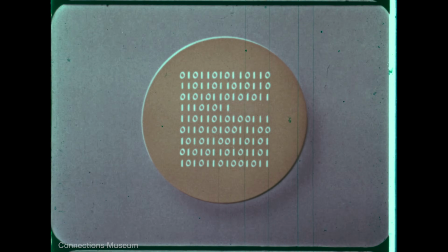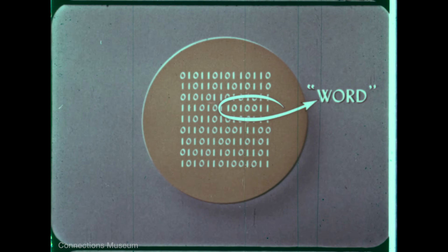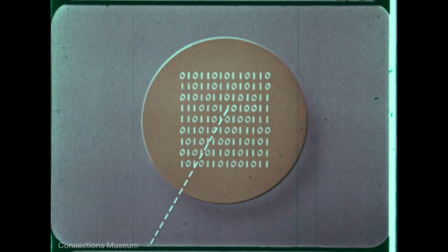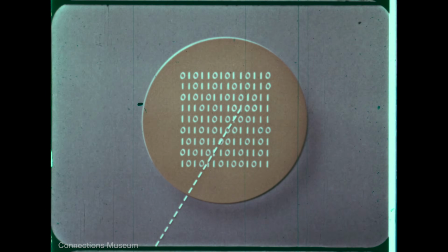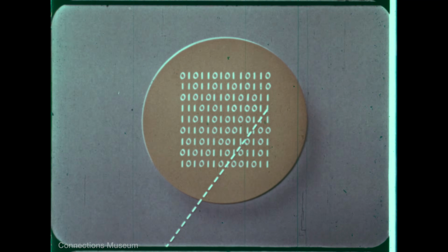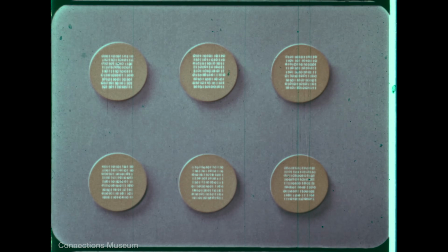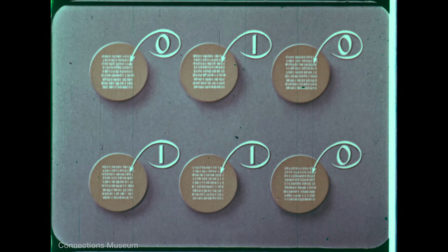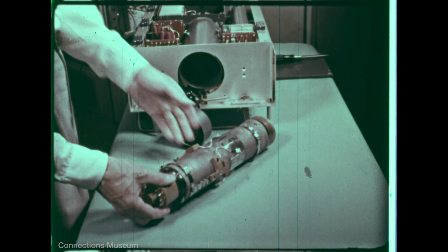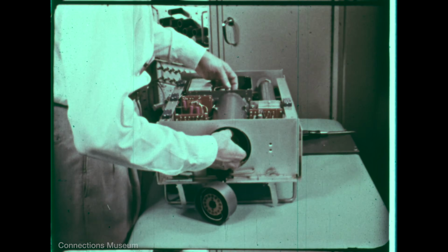Bits are stored on the mica surface one at a time. Successive bits may represent a word, which may be read and regenerated by directing the beam to the address of the first bit and scanning succeeding positions. Sometimes several tubes are connected in parallel, so that one bit for each word is at the same address on each mica surface. The barrier grid tube is an extremely fast temporary memory.